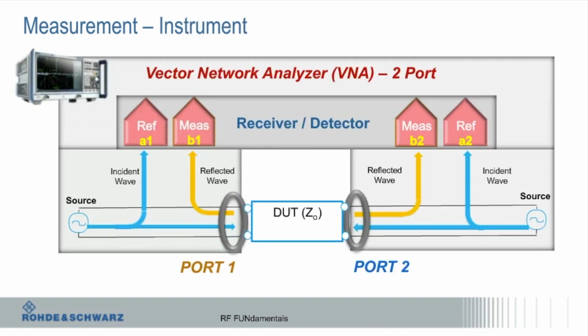So, looking inside a VNA, now we're taking a VNA apart. To make these measurements, the key things I need are a source, at least one coupler, probably two, and in this case I have two, and measurement receivers. Basically, I stimulate my device. If this is an amplifier, for example, I send a signal in. It samples the signal as it goes out, so I measure the amplitude and phase here, then some signal gets reflected back, and I measure its amplitude and phase here. So when I measure S11, I'm just doing a ratio of these two things, right?